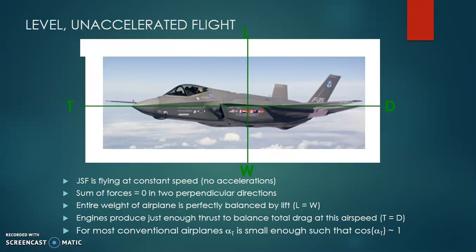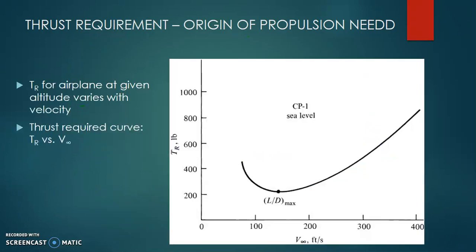So once we have understood this basic concept in the previous lecture, now let us look at this important graph. This graph is about L by D for various velocities versus the thrust. Very important concept. When we start plotting our thrust with velocity, you actually get a parabolic curve, a semi-parabolic curve, which is almost like an economic competition curve that people often use in economics. The question we have to ask ourselves is why? And the answer is very simple.